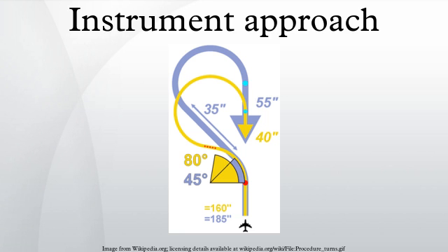When flying a back course, the course deviation indicator needle deflects to the opposite side with certain types of equipment. This reverse sensing means that the CDI in the aircraft indicates the opposite of what the pilot is expecting on a standard localizer approach. That is, the CDI indicates to fly left when the aircraft in fact needs to fly right to intercept the approach course, and vice versa. Using the CDI, if the needle moves away from center, the aircraft should be flown away from the needle toward the center in order to re-intercept the correct inbound track.